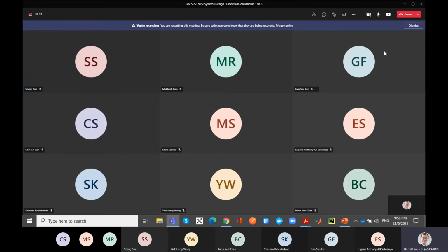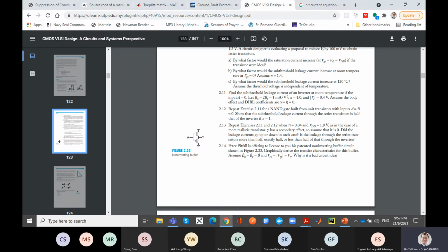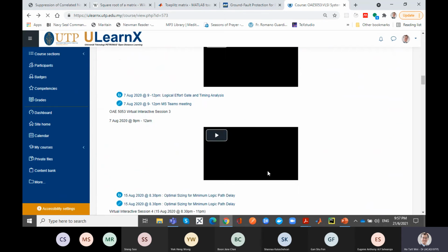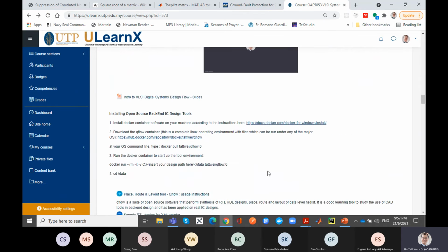I think some of your friends, like Shufan, also mentioned you get DRC failures. My suggestion is, as long as you have post-static timing analysis and you can extract the SPEF file, don't worry about DRC failure. This is how I'm going to distinguish it, because I have several goals for asking you to do this assignment. One of the major goals is just to let you experience what it's like doing the place and route and going all the way to the end.